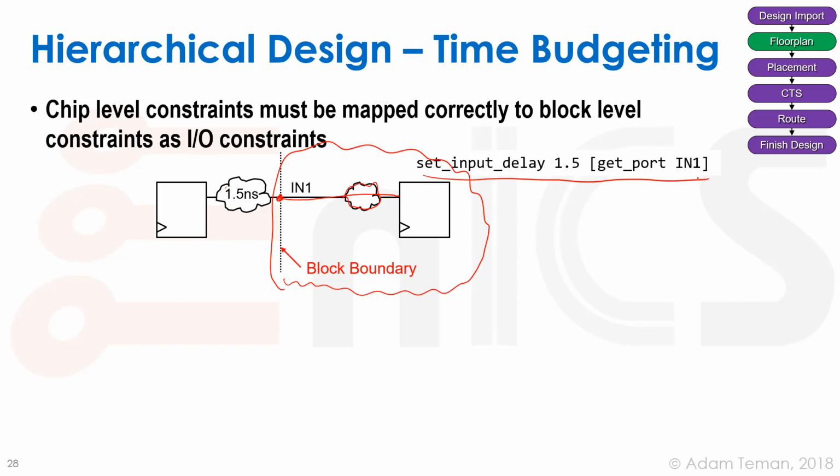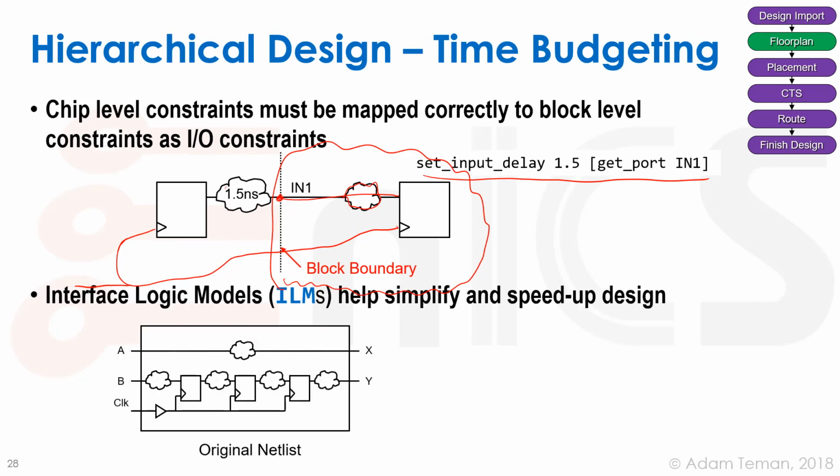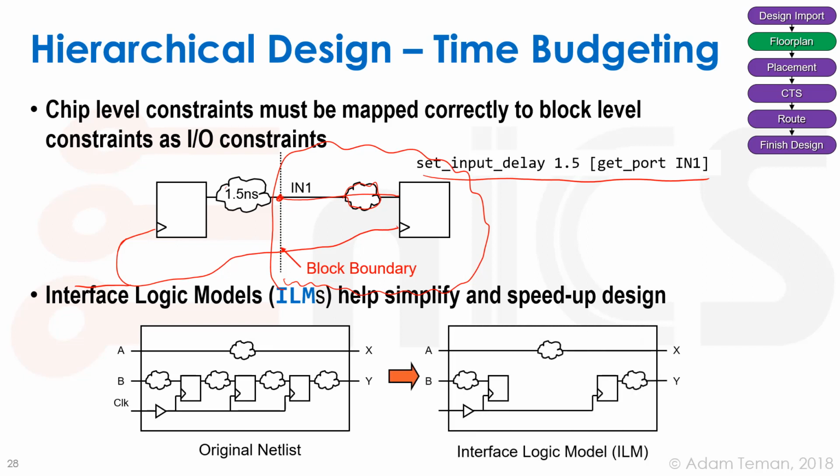If this is the border of our chip, we don't know what's going to be connected out here. We have to meet some sort of standard that defines what our hold and setup delays outside the chip are. But when we're talking about hierarchical design, we're eventually going to know about this flip-flop, this logic cloud, and the skew between the clock nets, because it's going to be the same clock that gets into both places.